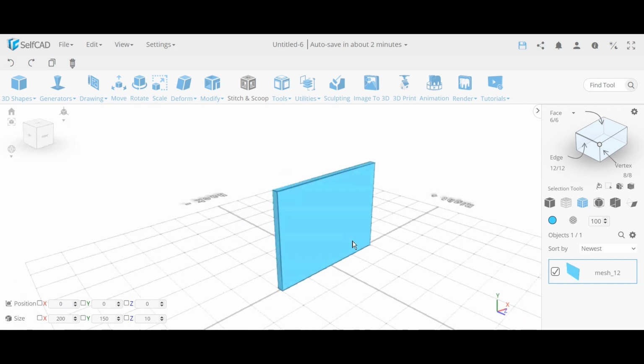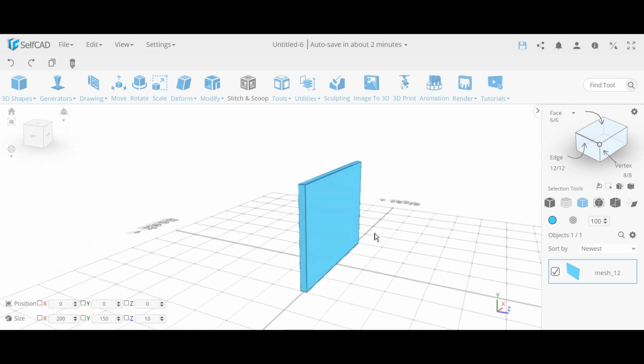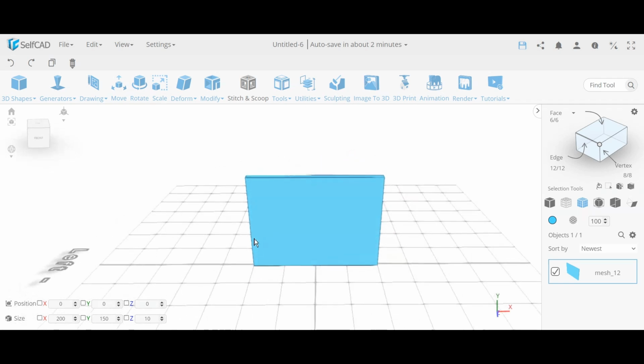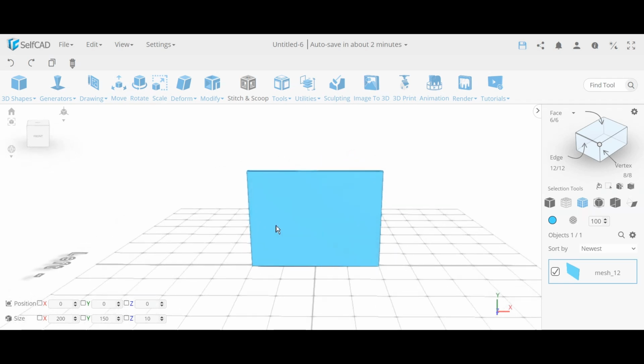Every design will be different, and I'm going to use a very basic thing, a simple cube, to show how to split it, but the design flow is always the same. If you want something to be able to move, you need to split it into two or more pieces, depending on the design, and then you need to create a distance so you don't have friction, so you have room to move.